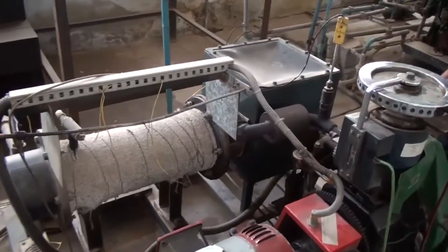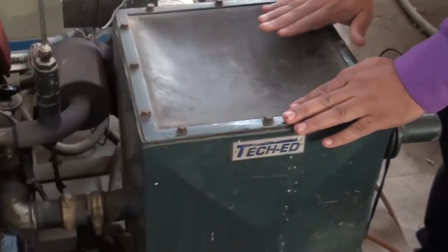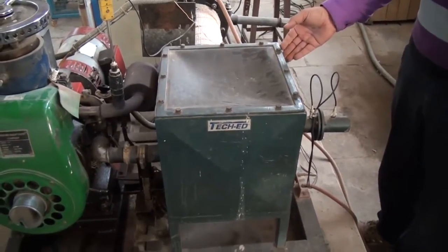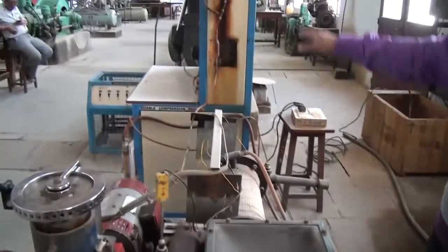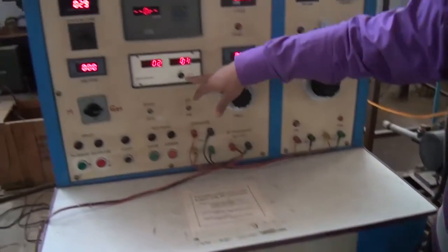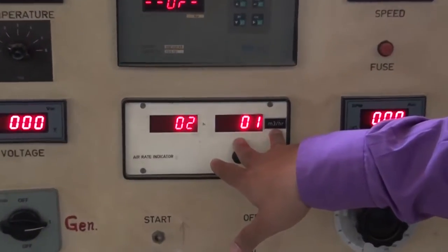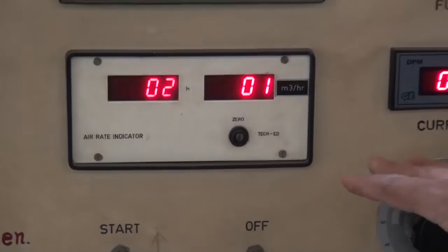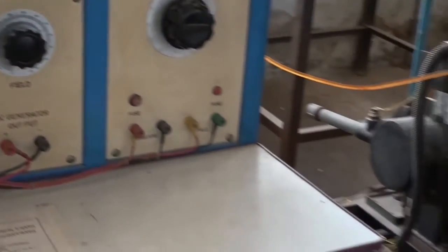Now on the other side, what we have is an air box, through which the air is passed and the measurement of the air is taken. So basically the air enters and the difference in delta H is calculated already. Through the electrical connections, the reading will be there on the panel. So through the air box and electrical connections, we get the amount of air consumed on this panel. Right now this is a dummy reading. This is in meter cube per hour, the amount of air consumed. So there is no need to calculate delta H, the coefficient of discharge, area, everything is fixed, and we get only a digital reading, the final reading on this panel. Now what else is there in this rig?